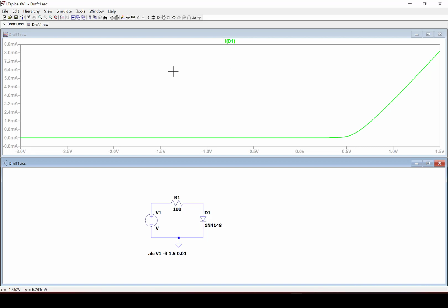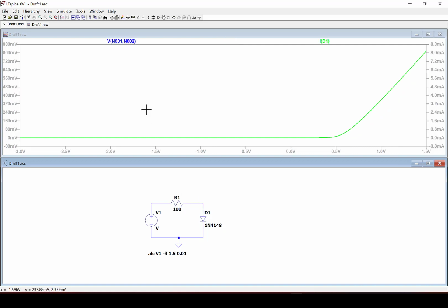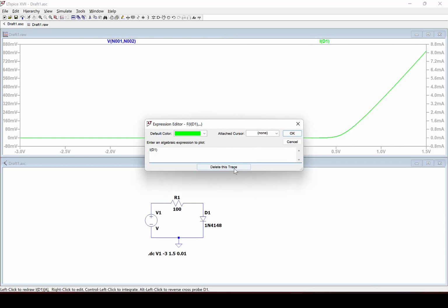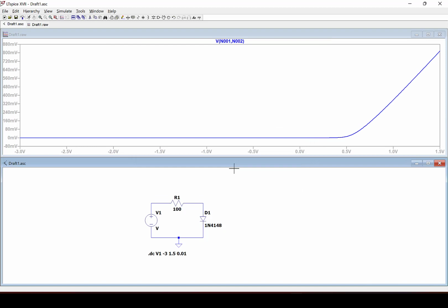Another thing that we can do, if you want, starting from this plot, is basically to see what is the current through the resistor. We can either place a current probe over here, or we can put a voltage probe here, and left-clicking on our mouse, keeping the button pressed, we can put the second probe over here, so that we can create kind of a differential voltage probe, and probe what is the voltage across the resistor, which is obviously proportional to the current through the resistor.